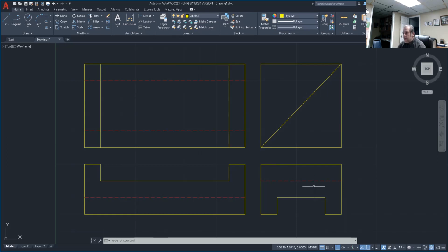Okay. Feature number 3 now becomes our holes. Now I'm going to show you an awful lot of stuff on the holes to maybe make it a little easier for you as you do a drawing. So our holes, which view, first of all, are we going to see them true size and shape? They're going to be circles in the top view. Here, they're going to be lines here. So I'm going to draw them in the top view right here.